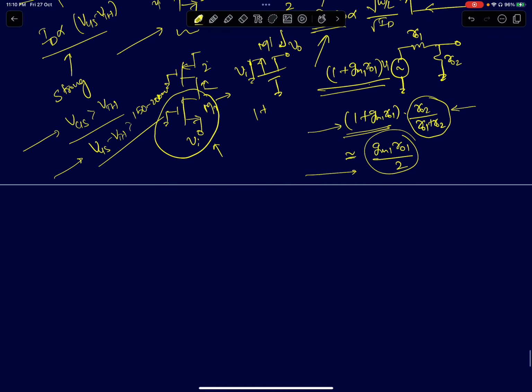Now, there are a few points which I'll explain now. Probably when I float this course on CMOS opamp design, I'll go much deeper into it. But right now, the expression for MOS transconductance is proportional to root of mu n Cox W by L times the drain current.